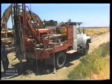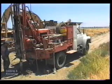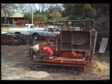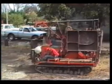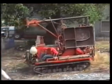Highway drill rigs, the most common, are mounted on the back of an industrial truck, allowing high mobility and minimal setup time. A highway rig is used for sites that are relatively level and easy to access. Off-road drill rigs are used when access to a site is unusually difficult. Typically, these drill rigs are either mounted on large rubber-wheeled trucks or on tracks. If an off-road drill rig cannot directly access a site, a helicopter may be used to move it into position.